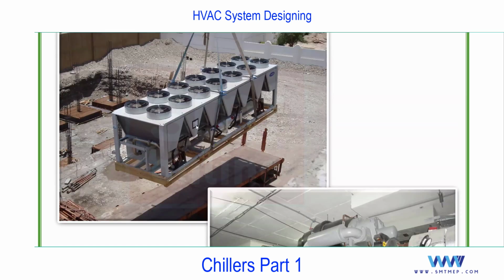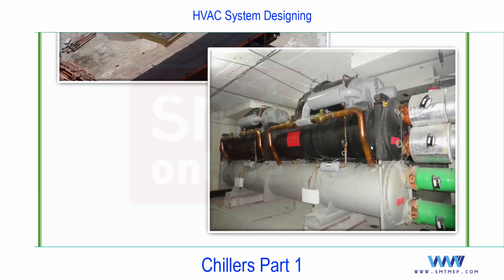Air-cooled chiller is like a cabinet and we are placing it completely outside the building. And this water-cooled chiller, you can find this is placed in the plant room inside the building, except the cooling tower. And what is cooling tower? We'll discuss. At this level, I'm just using some new terms and terminology. If you're not aware, don't worry. At the end of this session, you'll get the clear idea about these two types of chillers.